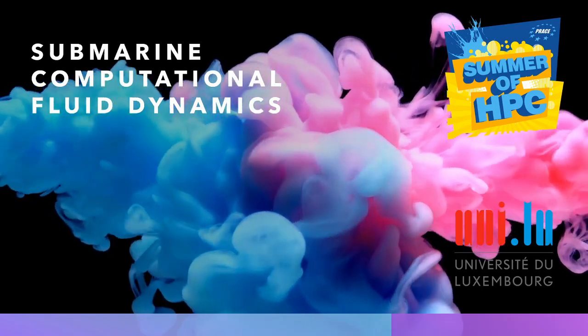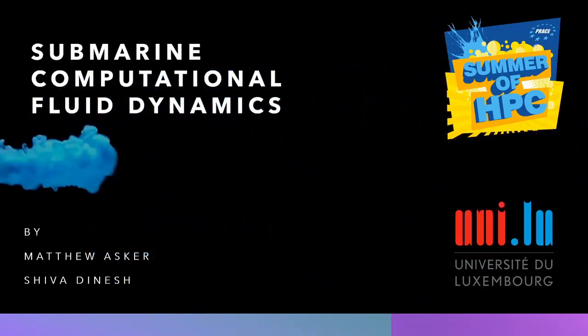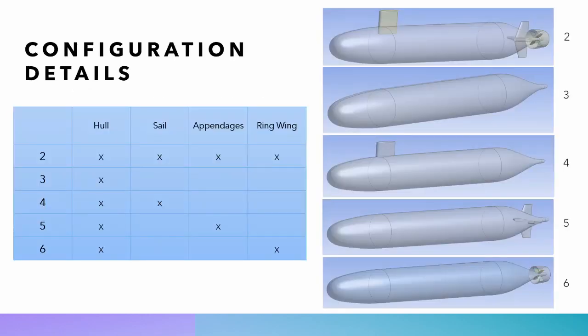Shiva and I have been working for the last 8 weeks on Project 2021, Submarine Computational Fluid Dynamics, and we'd like to share the progress that we've made so far. Our task was to investigate the effects of different turbulence models on CFD simulations of the DARPA SUBOFF submarine, also considering different configurations of the submarine and drift angles that it travels at. We do this by considering the drag coefficients of each setup and looking at the distribution of the turbulent kinetic energy. Here are the 5 configurations we considered.